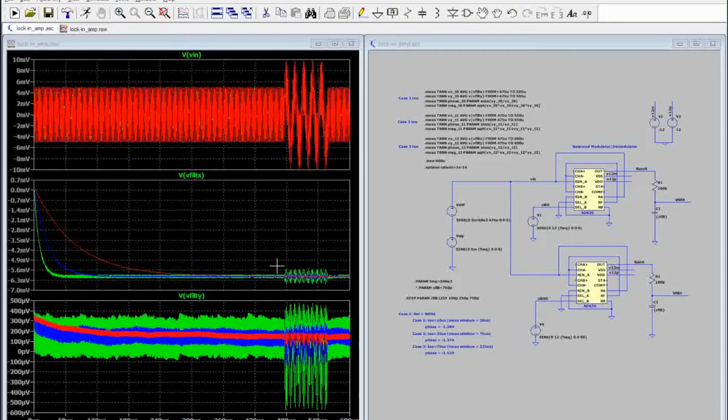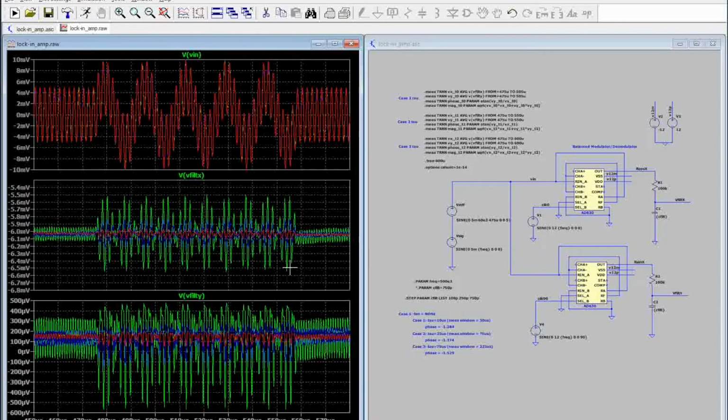If you look at the X component, or the cosine component, the in-phase component, you'll see that the 60 kilohertz interferes in such a way that it creates points on both sides of the 6 millivolt average level. And the Y component, the quadrature component, is doing the same thing. It's distributed around the 0 value. So if you take the A-tan function of these two, you're going to get a value that is close to the original value.